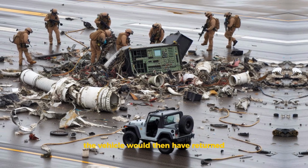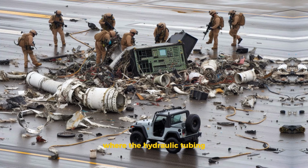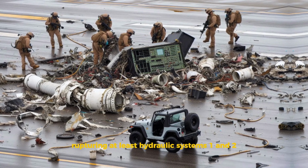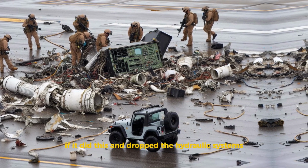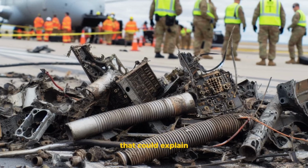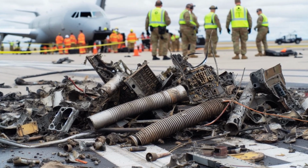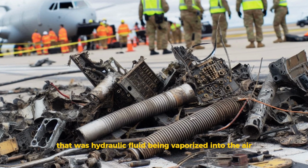The vehicle would then have returned, crashing into the aft pressure bulkhead, where the hydraulic tubing connected to the flight controls, rupturing at least hydraulic systems 1 and 2, and possibly more. If it did this and dropped the hydraulic systems, that could explain the eyewitness account of white puffs of smoke as the aircraft climbed away. Most likely, that was hydraulic fluid being vaporized into the air.